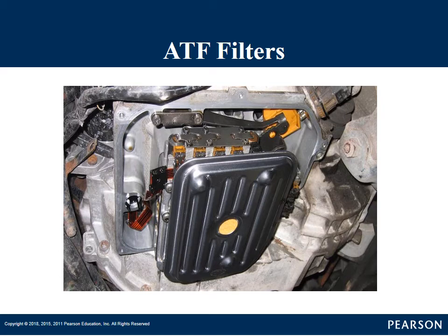Very, very common. In order to service these, you would unbolt that pan. If it had a drain plug on the pan, you would drain the fluid first. A lot of times it wouldn't. We'll talk about this when we talk about servicing. But you get that pan, the fluid out, replace that filter, put a new gasket on the pan, put it back on there, fill the transmission back up. This is the most common.